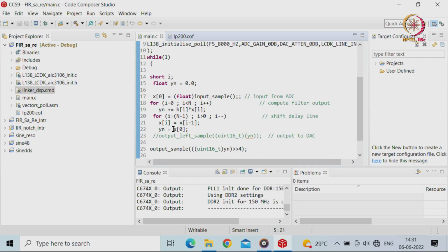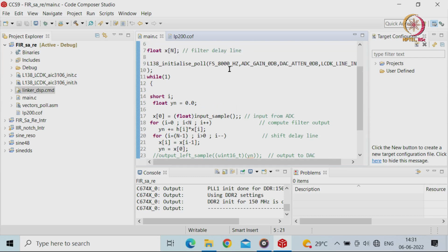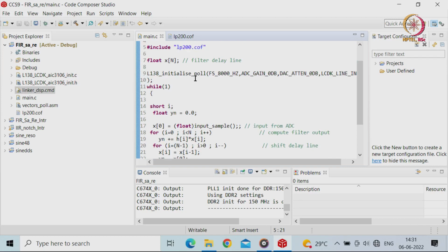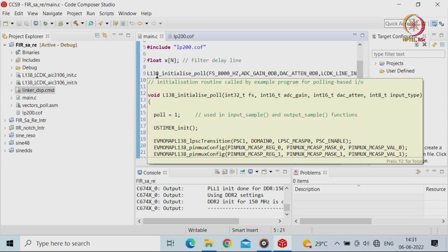So, I have to go for a very high order filter. Here, although it shows it is a 200 order FIR filter, I may still have to increase it. But as when we took up the stability of the filter for FIR, although we said it is stable, at least up to the 256th order it may remain so, but beyond that it may become unstable. So, it is better to design all your filter orders for FIR on the board to be less than or equal to 200. What I tell my students is not to go beyond that, somewhere around 120 to 150 is what we do.